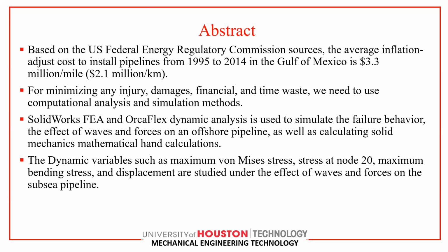The dynamic variables such as the maximum volumetric stress, stress at node 20, maximum bending stress, and maximum displacement are studied under the effect of waves and forces on the subsea pipelines.